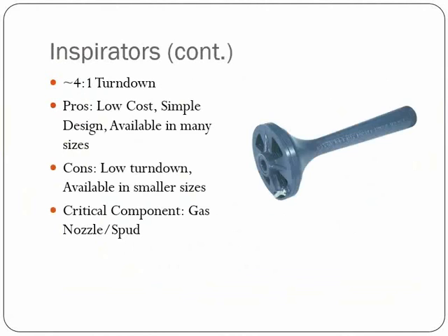So inspirators have approximately a 4-to-1 turn down, and I think that's on a pretty good day. So the pros of inspirators are that they are a very low-cost, simple design. It's a scalable technology, so you can use it in smaller applications down under 100,000 BTUs or into tens of thousands of BTUs. And they also are available in much larger sizes as well.